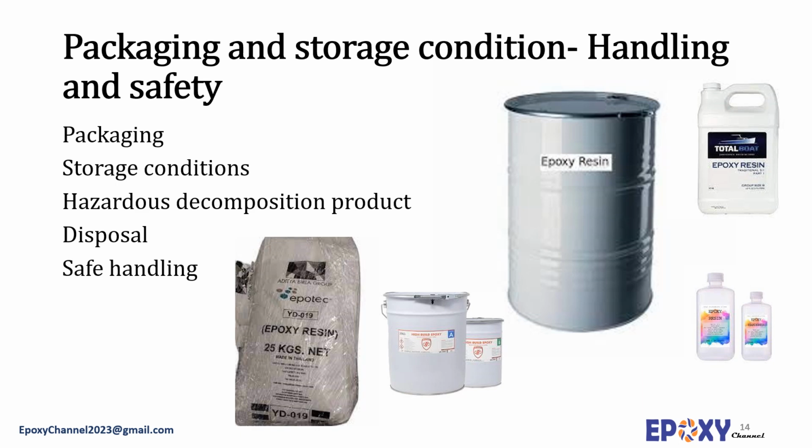Under the storage and handling section, often the recommended conditions for storing the epoxy system are presented. Other information includes the shelf life of the product, hazardous decomposition products, and disposal guidelines. The storage condition is greatly dependent on the type of the product, and a temperature range of 2 to 40 centigrade is a common recommendation for typical epoxy resins.